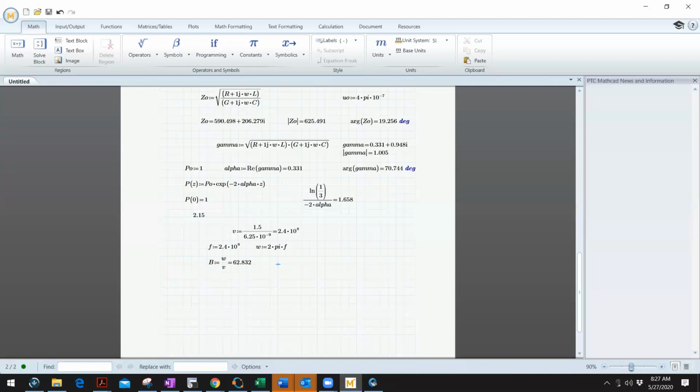Well, look, you remember alpha can be in Nepers per meter, right? Or it can be in what? dB per meter, correct? Y'all with me? Now in dB per meter, I want to be careful that everybody follows me. If it is in dB per meter, then alpha times the distance z would be the total attenuation in just dB.